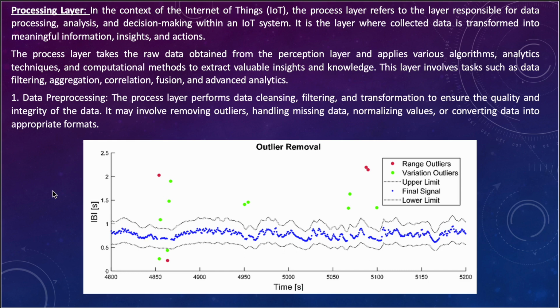All the sensor manufacturing companies, if this is something that has been taught in IoT, you will see that they have their own logs or documentation for each sensor, and in those documentations they normally show what kind of error could be there in the reading. It's not a big error, but it is there. If you take, for example, a temperature sensor, some temperature sensors perform in between, let's say, minus 40 degrees and 120 degrees Celsius, right? So sometimes when it goes closer to the limitations of that sensor, the error rate may go high.